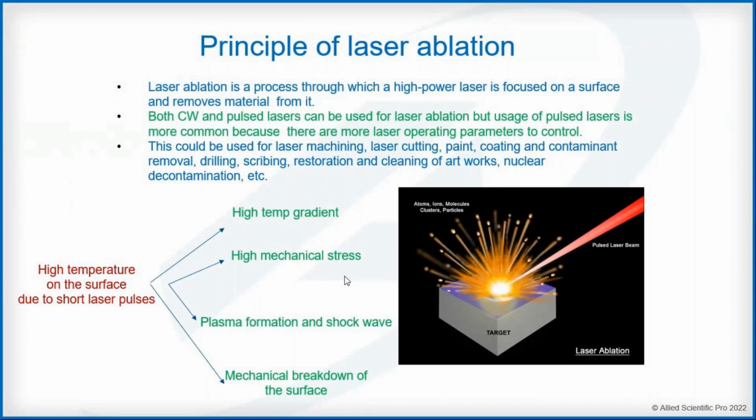The high temperature would create a high temperature gradient, high mechanical stress, plasma formation, and a shock wave. This shock wave will blast the surface and cause the mechanical breakdown of the surface. So this is basically the principle of laser cleaning.